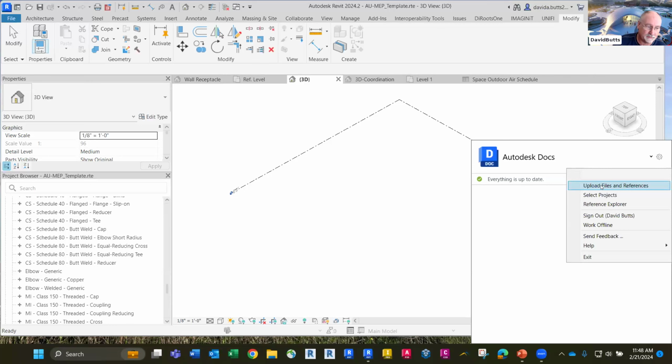If you're doing this with Revit files, only 2023 and newer files can physically be moved without recreating them. Yeah. Anything before that, the path was hard coded into the files. So when you want to move an older Revit file like 2022 or earlier, you save it to your local hard drive, open it up, tell it you're going to work in it temporarily, and then say save as cloud model, and that recreates it as a central file in the new location. Doesn't take a lot of time, but if you've got 100 Revit models on a project, it can be a little bit of time.